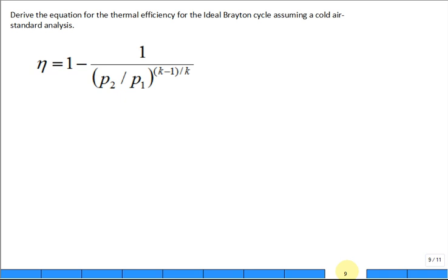So this is that equation. It's the thermal efficiency. And it's really interesting that you can get it wrapped up, I know there are some assumptions behind this equation, into such a simple expression. It's just the pressure ratio and K. And K is typically just 1.4, because that's what you would deal with, cold air. So it's just a function of pressure ratio. Isn't that almost mind-boggling? The first time you see it, it can't be that simple, but it does work out to be that simple.